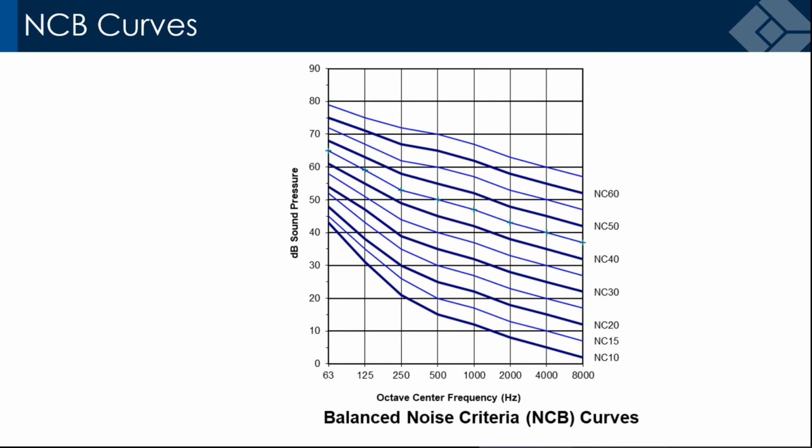Eventually, you're at a megaphone. So putting barricades around a loud piece of equipment. Like let's say we've got an air-cooled chiller or air-cooled condensing unit outside. When you put a wall around it, it does have a shadowing effect, especially at high frequency. And when you calculate that, the amount of noise you reduce it by depends on the extra distance going over the wall versus going through the wall. And it's a relatively long equation, but it's really simple in the spreadsheet that we have.